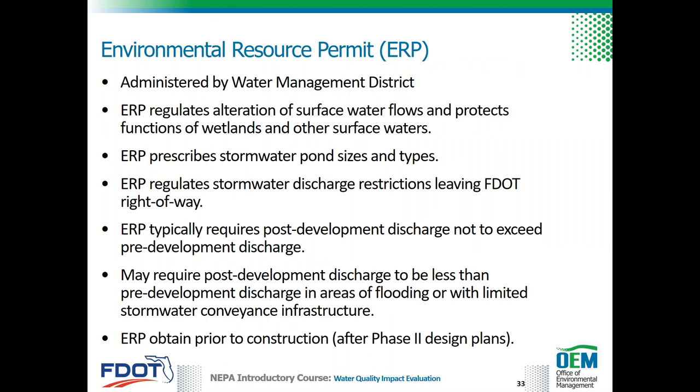Additionally, Florida requires the environmental resource permit to regulate activities involving the alteration of surface water and to provide for wetlands and other surface water protection. The environmental resource permit is administered by the applicable water management district and prescribes stormwater management requirements. Generally, for transportation projects, the environmental resource permit requirements regulate stormwater discharges leaving FDOT right-of-way.